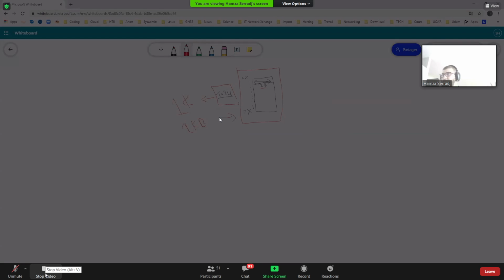It's 1000, right? And it's not 1 kilobit. Be careful, so this is different than this. This is 1 kilobit, if I had 1 bit per address. Now I have 8 bits per address, so it's 1 byte, right? So I have here 1024 bytes, 1 kilobyte, right?